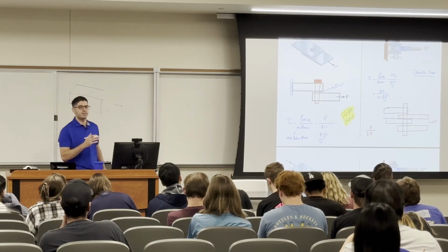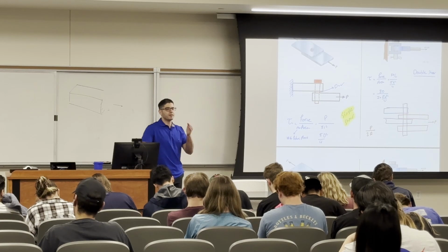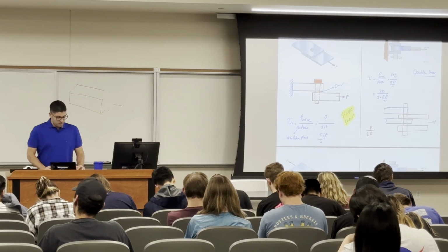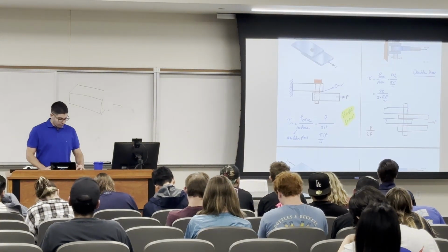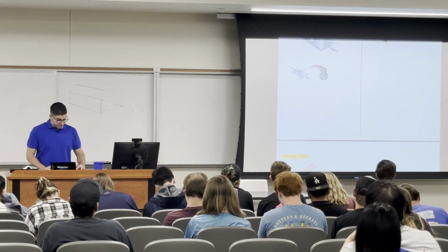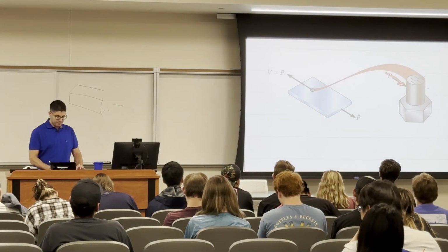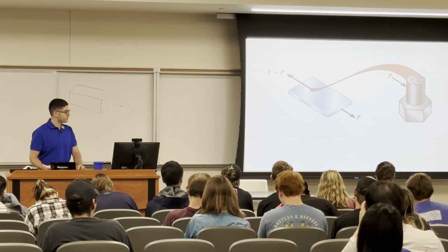As long as you understand how many planes of failure, or how many load paths I have, then you can divide the force by it. Is that clear? Okay. Yeah, this was the failure, and this is the force that came, and that's how it's going to be distributed over the cross-section of the bolt.